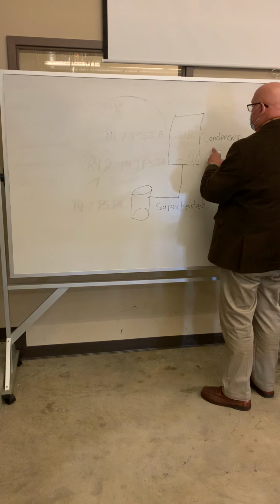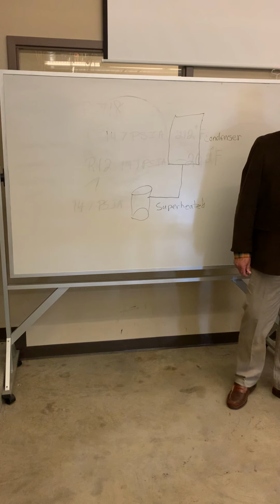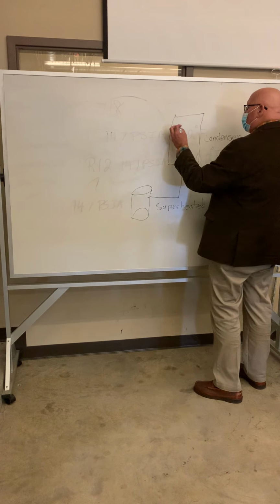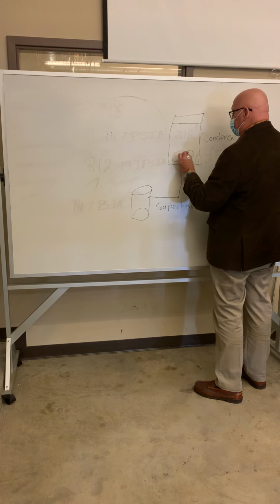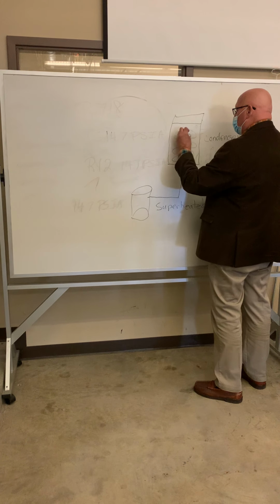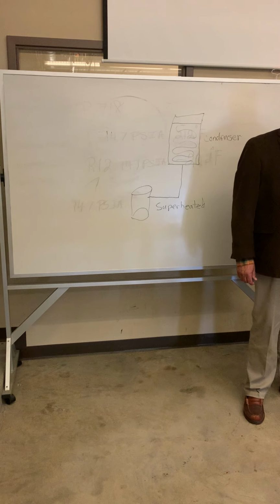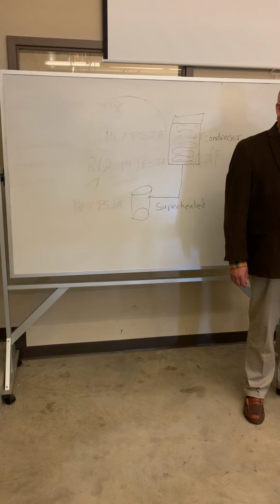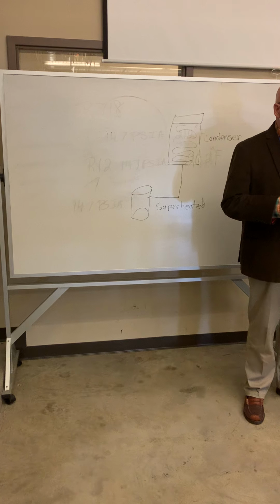So it goes through this condenser and it gives off that heat, all the way to the very end of this coil. It's serpentine. Serpentine means it goes like this, like a snake, right? It gets to the very end of that condenser, where we've removed all the latent heat, that hidden heat that's measured in British thermal units, and then we begin to reduce sensible heat.